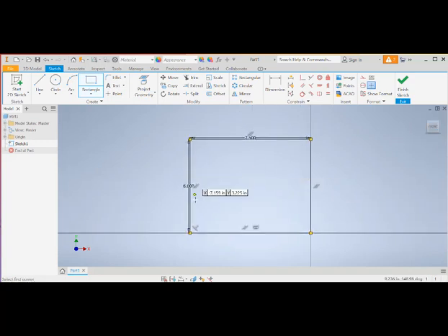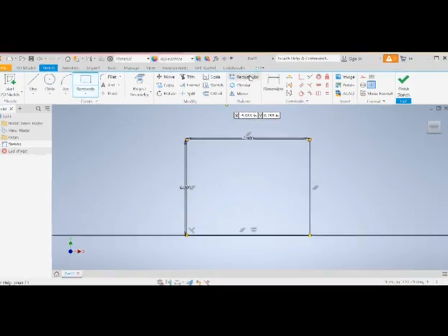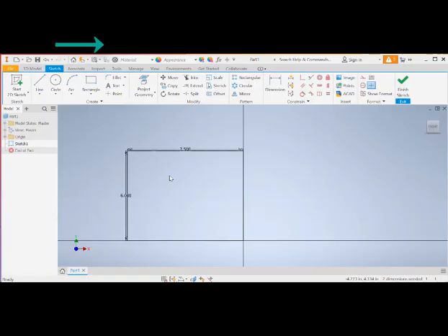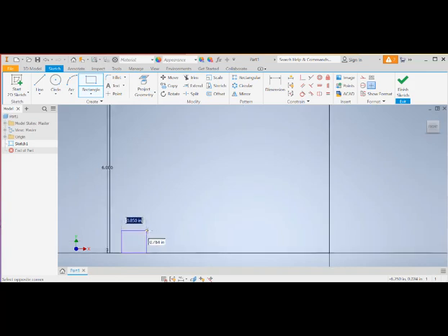So I bring it into view, and now here we're going to do some new things with something called the rectangular pattern tool. Now what I'm going to start with is a square that will represent the size of a coin. So I'll use the rectangle tool, and I'll use the dimension tool to tell it how far away from the edge of the frame that will be. I could have put those dimensions in right away, but let's make sure it's 1 inch square. So 1 inch that way and 1 inch this way.